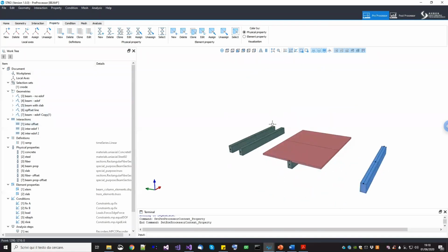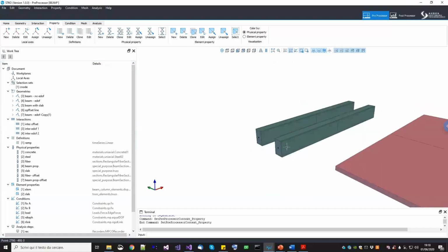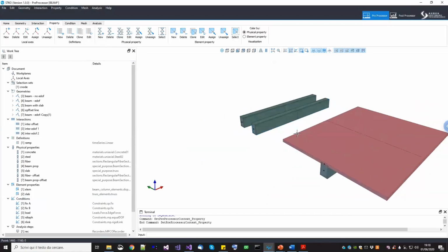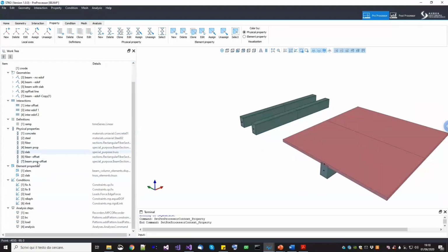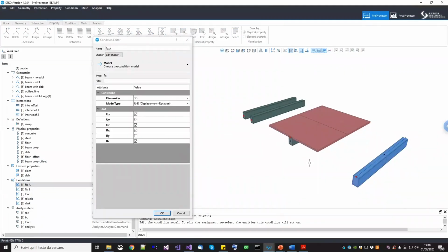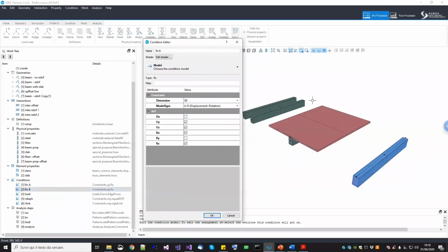It is a simple, simply supported beam. Okay, so the fiber, you can find the fiber cross section here. It is, I think, 4 meters. Then I split it in the middle just because I want to use the middle point as a control node for the displacement control. And then the boundary conditions are pretty easy. So at node A, the first node of all the examples, everything is fixed but the out of plane rotation. While on the other end, also the in-plane displacement is allowed. Okay, so you create a simply supported beam here.